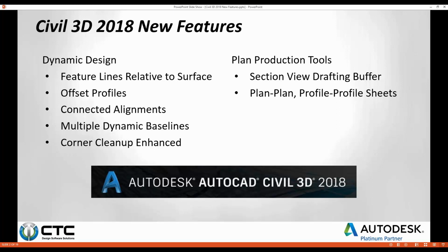And then lastly, on the plan production side, where we had plan-only sheets for things like exhibits or overall site view, or plan profile sheets, we've now got options when we're creating view frames to have a plan over plan or profile over profile sheet. And we've got new templates out of the box as well to handle that or to modify for your own company.